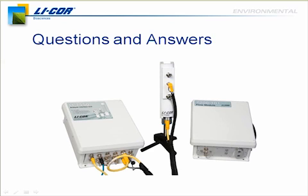Yeah, Bill, let me take that one. That's a good question, Katerina, but there are a couple of issues that could arise from doing something like that. The first one I can think of off the top of my head is that if you have this shroud inside the 7500 and you have a pump and a small tubing pulling the gas stream through your 7500, you're going to create a negative pressure up there, and potentially you're going to be pulling outside air in through around the gaskets of the shroud and contaminating your sample that way.